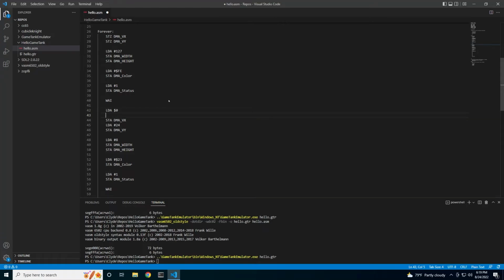Then, we'll perform some addition to update this value. The instructions needed for this are CLC and ADC. ADC stands for add with carry. If you've ever done addition on paper, you'll be familiar with the practice of carrying a digit to the next column. When add with carry is used, a carry switch is set if the result would be greater than 255. If the switch is already set, then an extra 1 is included in the sum.